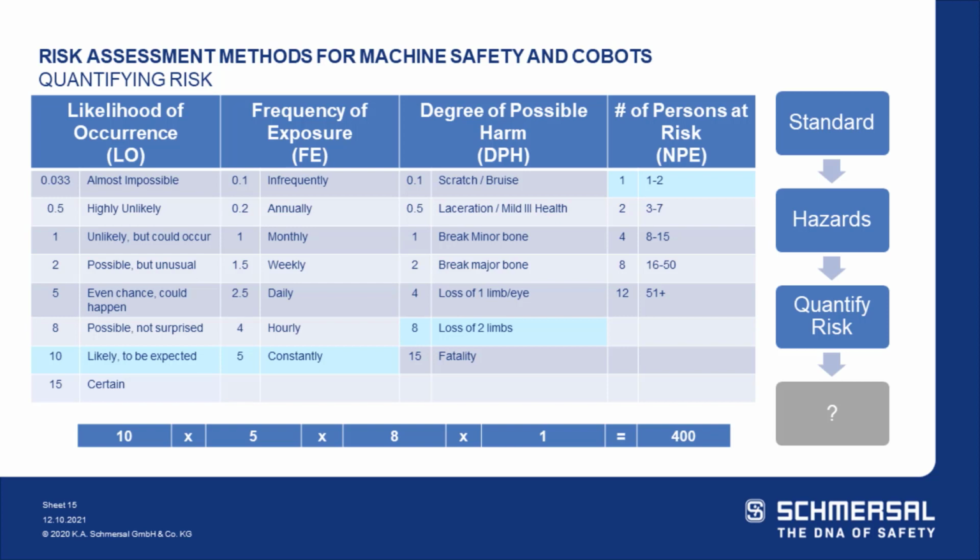In this story, what ended up happening was, if the part went in at a little bit of an angle and wasn't placed correctly, and you hit reset, it would potentially break a die, I believe, and it stopped production. And that person did not want to stop production, embarrassing or for whatever reason. So when they put it on an angle, they hit reset, they saw it, and they reached their hand in. The reaction was to reach their hand in and put it correctly in that system, and that's when the amputation happened. So my point in telling you this: put your mind in a system like that. It's a reaction. It's not necessarily where they're trying to hurt themselves.